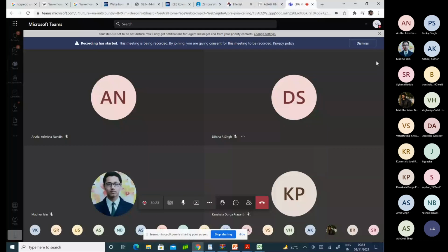The meter cannot sense the position of the core above null or below null. Okay, it is a big problem. You have some displacement, and the output voltage will show the displacement, but it cannot sense whether it is above null or below null. And then the meter cannot follow the rapidly varying core position. These are the two issues. For a rapidly varying core position, the output voltage can be an amplitude modulated sine wave, and then demodulation is necessary. Phase sensitive demodulation is necessary. We are coming to the next slide to discuss that.